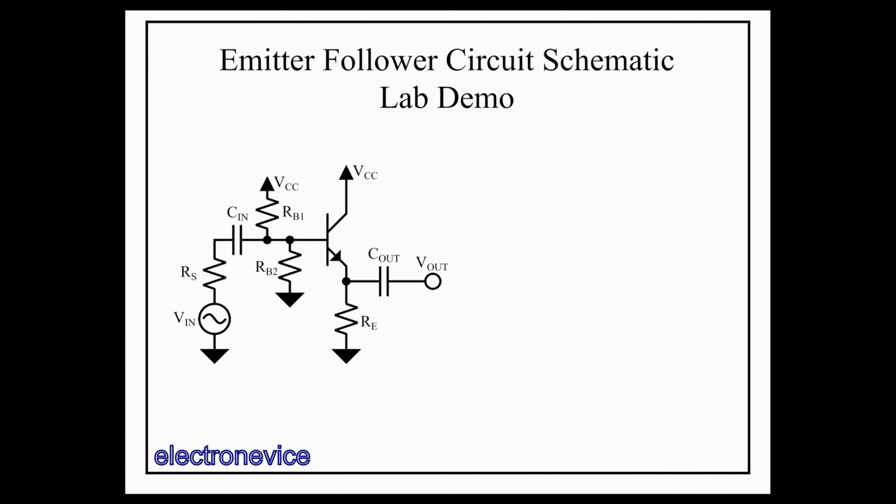Here's the schematic of the emitter-follower circuit with the biasing network we discussed in part 1. We'll be using the 2N3904 transistor, as I used in the common emitter demonstration. To start with, we need to come up with some requirements for our circuit. As this class of circuit is designed to produce an approximate gain of 1, with good buffering characteristics such as low output impedance and high input impedance, let's assume a few parameters for the system.